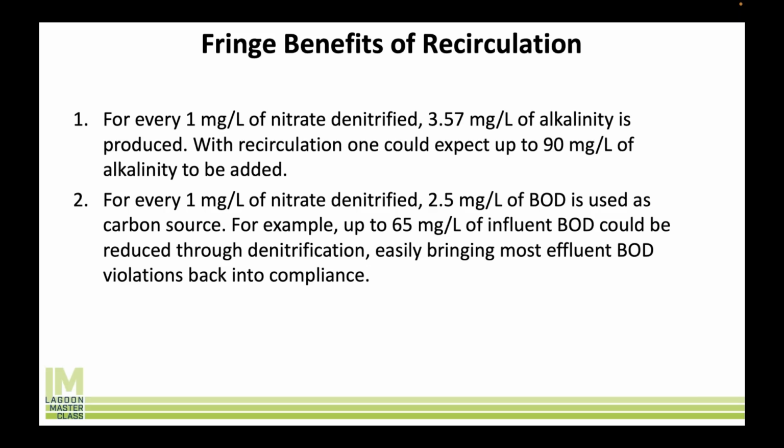Secondly, for every 1 milligram per liter of nitrate denitrified, we reduce BOD by 2.5 milligrams per liter. And we do this without adding any oxygen at all, right? So I like to call this free BOD removal, which is awesome, right? So in some cases, if you're struggling to meet a BOD limit, for example, you could remove almost up to 65 milligrams per liter by denitrifying, just by doing that.